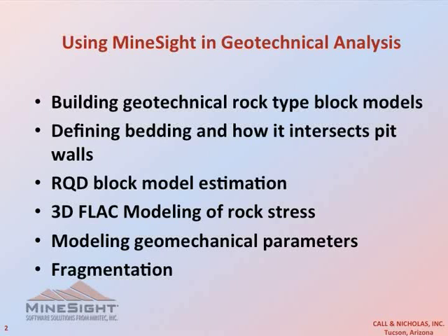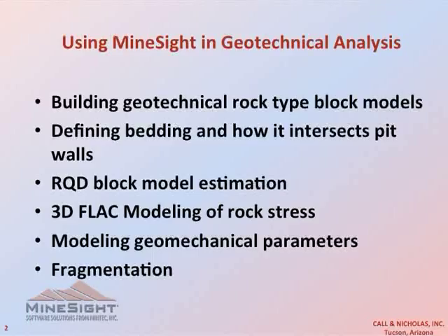One of the other things that we concentrate on a lot is defining bedding and how it intersects the pit walls. It's pretty critical in sedimentary units for these deposits that we know what the bedding orientation is, so you don't have an adverse bedding orientation to your pit wall.